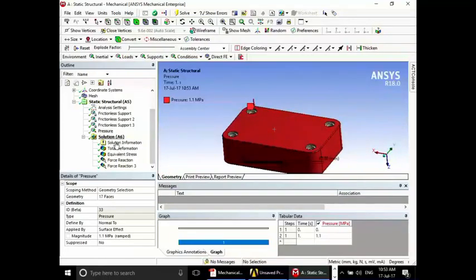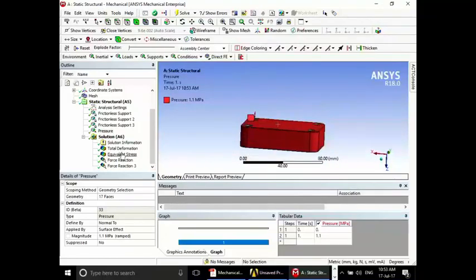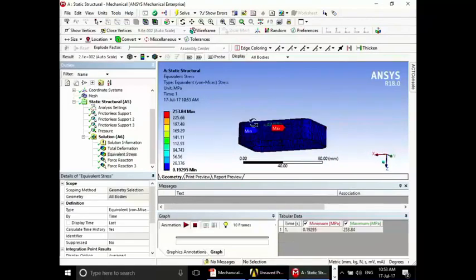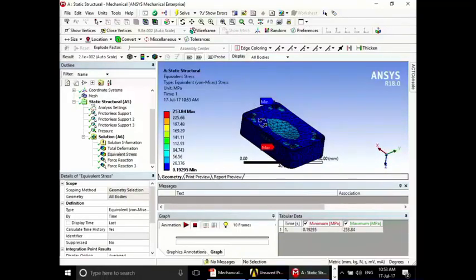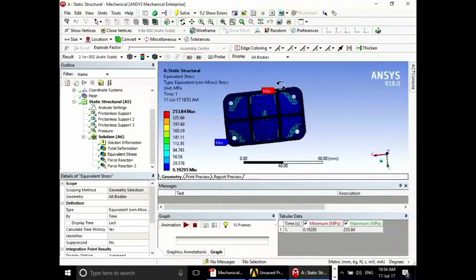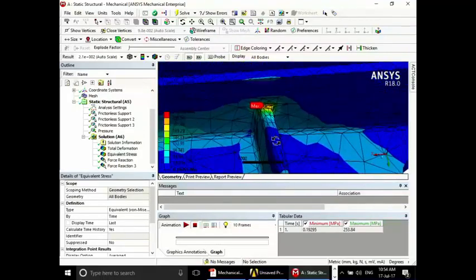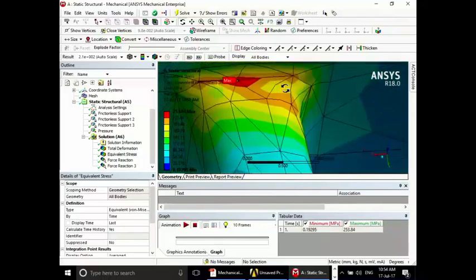Okay, so they're probably about the only real checks on this particular model that you can do. And they make sense, so that then you can trust that the other results you're getting should also make sense. Okay, so when we're post-processing, you notice that this contour bar doesn't have very many colours. Because there's a high stress region on the underside here, that's where all the colours are sort of focused, if you like.